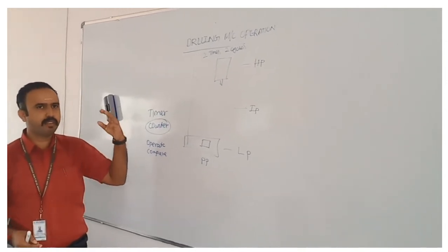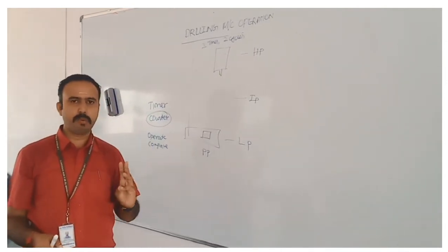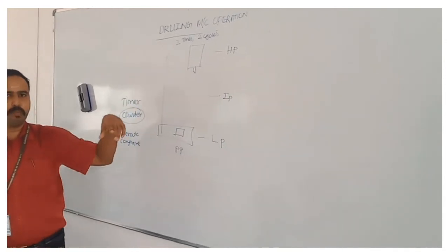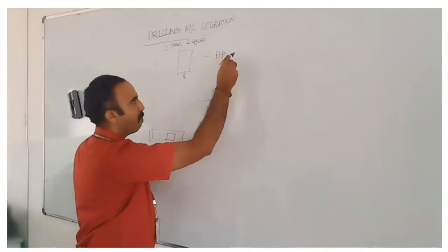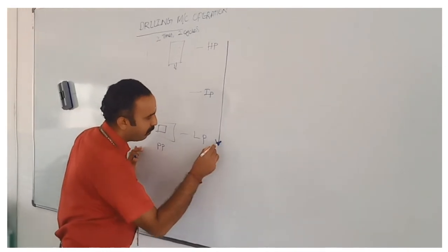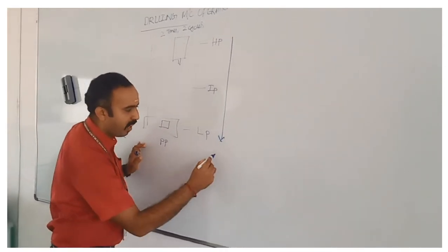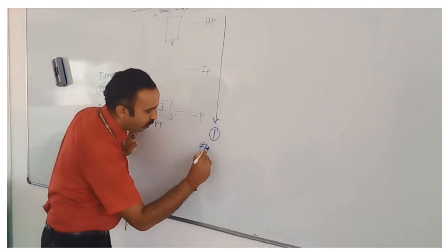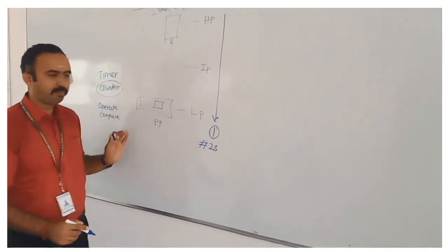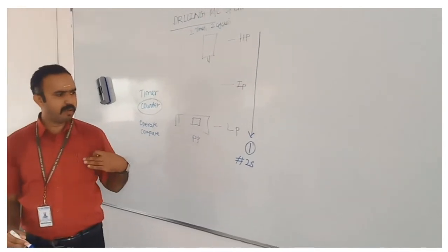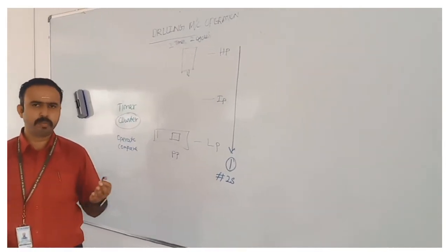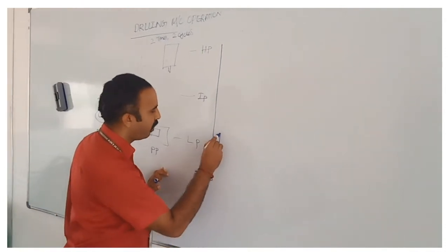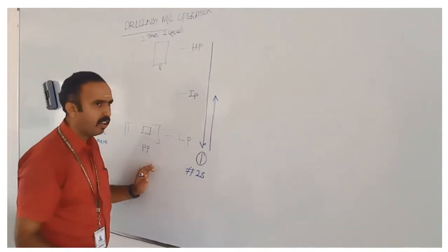When I press the push button, the head should be in the high position and the workpiece should be there. If that condition is met, what will happen? Immediately it will come to the low position and it will start to drill by waiting in the low position for 2 seconds. And it checks whether my drill hole is proper or not. I am not satisfied, so once again it will go to the intermediate position.